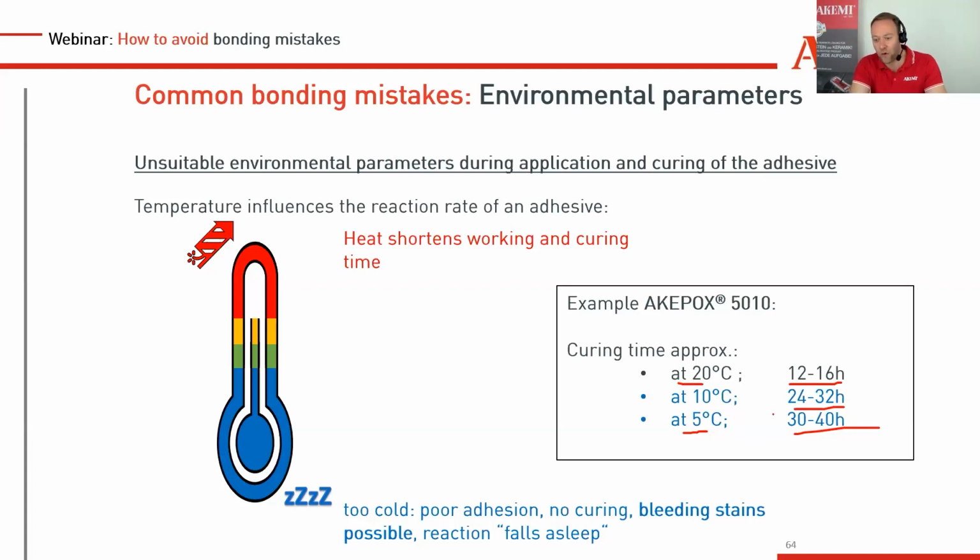So when you have to work with an epoxy outside and it's maybe 5 to 10 degrees, take your cartridge out of your workshop, so the glue has a proper temperature, and go with a gas flame and heat your stone. 20, 30, 40 degrees, no problem. The stone keeps the heat for at least, let's say, 30 minutes. And this usually is enough that the epoxy gets its start reaction.